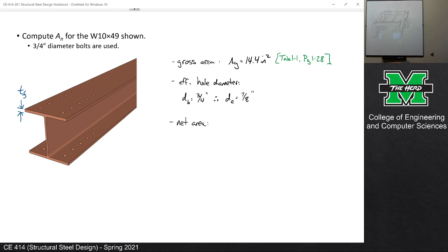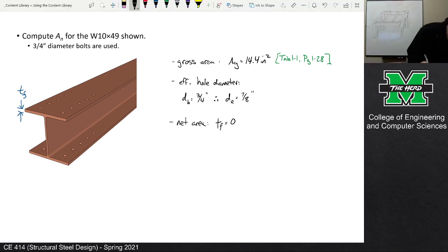We use the decimal value. T sub F is 0.560 inches. And we also got that from table 1-1, page 1-28. So, therefore, the net area is the gross area minus...